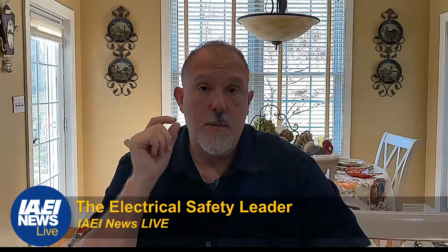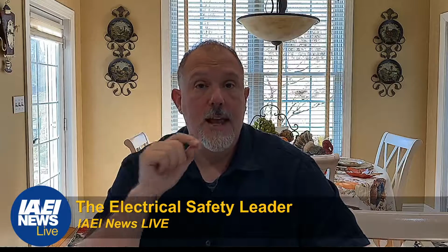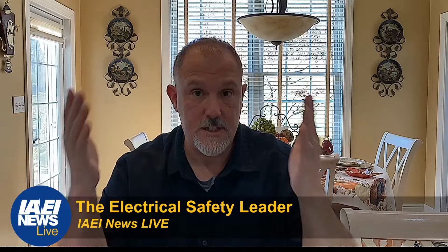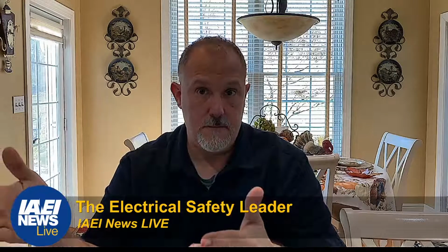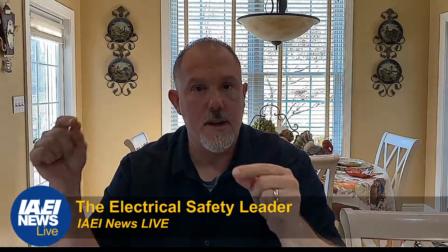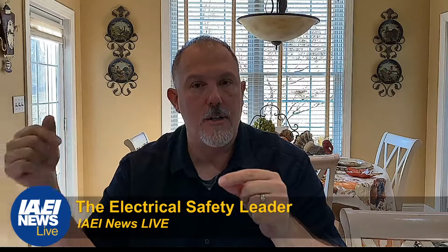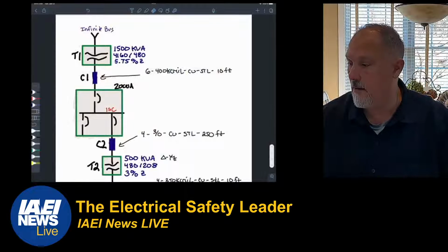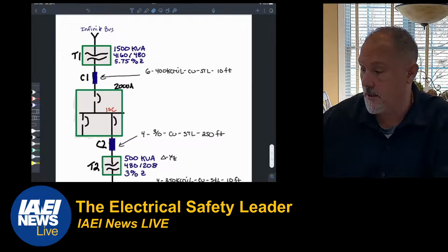So what we use is what we call per unit, and per unit lets me add all of my impedance values together because they're all percentages of base values. I'm going to walk through what those base values are, how we calculated those for this power distribution system. It's a small system, and we're going to do that right now. So let's take a look at what our system is.